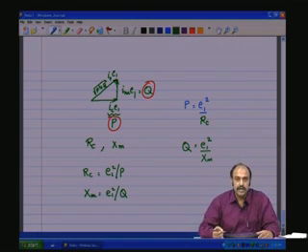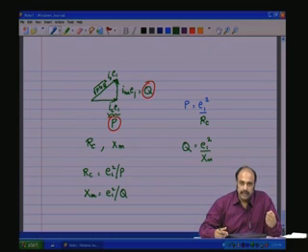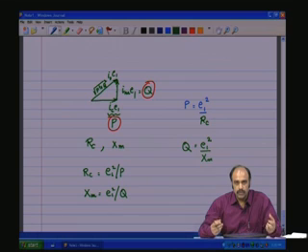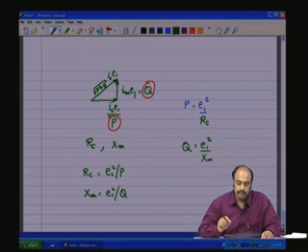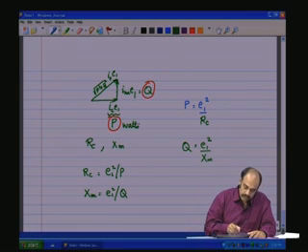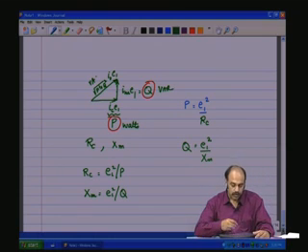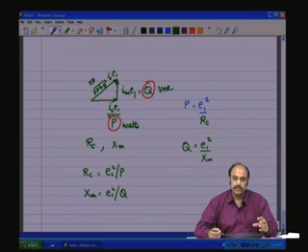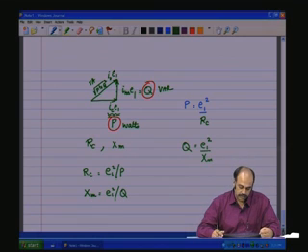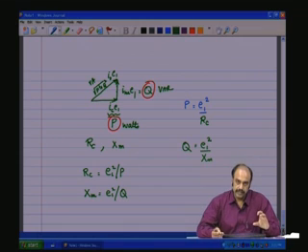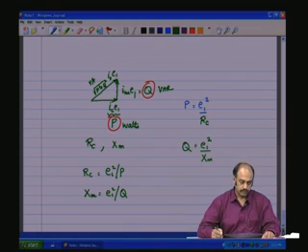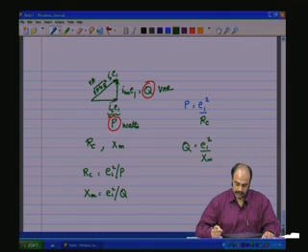So, measuring the active and the reactive power, that is measuring I0 and Eg voltage, capturing it on an oscilloscope, and then computing the P and the Q, that is the active power component which is watts, the reactive power component which is VAR, and this of course is VA. One can compute RC which is the core loss component, and Xm which is the magnetizing reactance component of the transformer under no load conditions, meaning when the secondary side is open circuited, there is no load connected across the two secondary terminals.